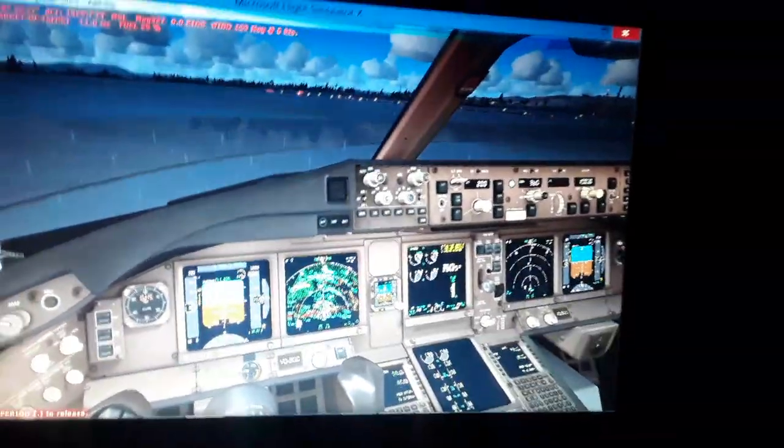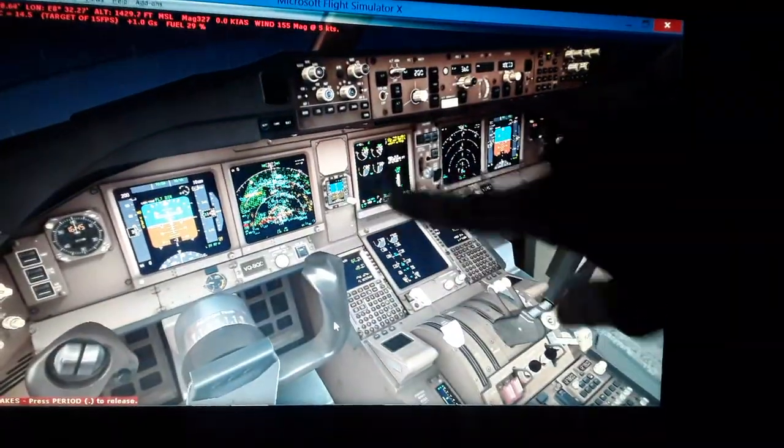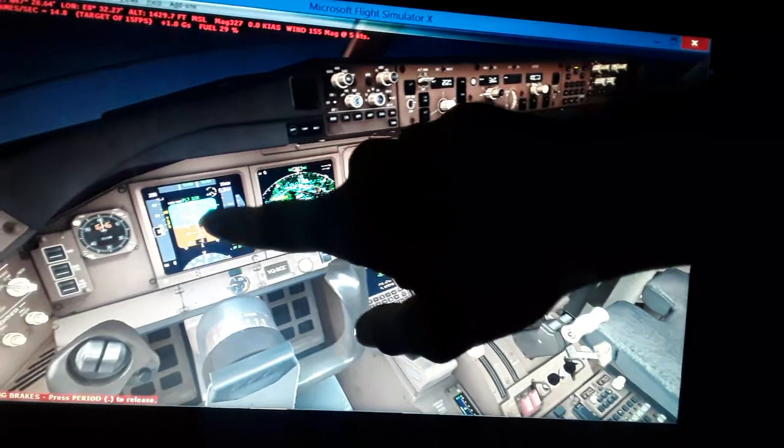And we're going to have also the localizer, horizontal localizer and vertical glide slope frequencies set for the desired destination airport and runway. So we're going to have a complete route or a complete flight path using the flight management computer over here, you can see, and we're going to use the flight management computer to input all the data that I told you before.